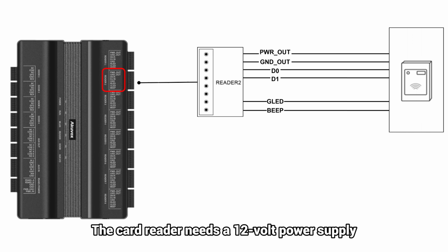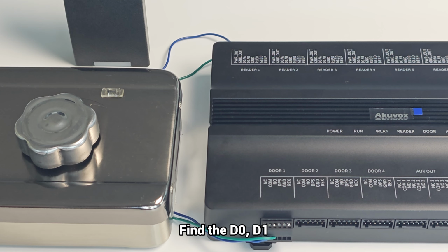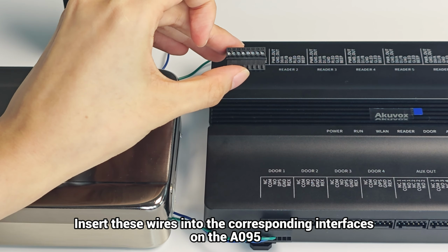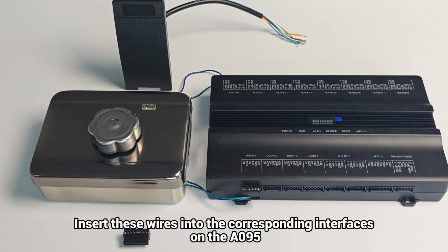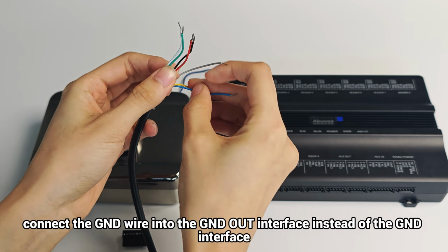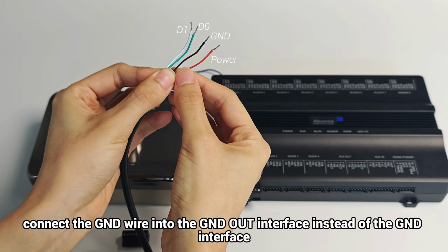The card reader needs a 12-volt power supply. We use A095 to power it on. Find the D0, D1, GND, and power wires of the card reader. Insert these wires into the corresponding interfaces on the A095. Since the A095 powers the reader, connect the GND wire into the GND out interface instead of the GND interface.